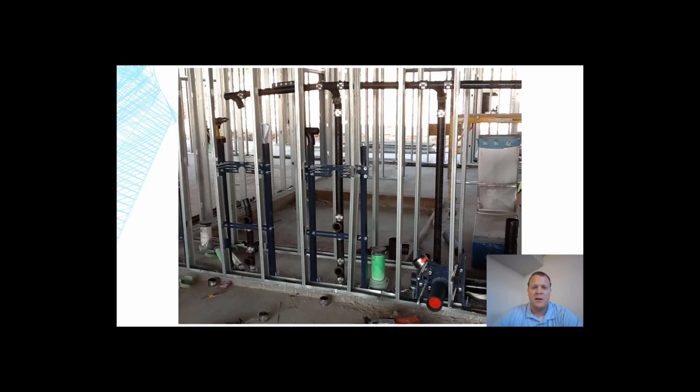So you can't just willy-nilly put in the electrical on the wall and then expect the drain waste vent to work. Not that there would necessarily be a lot of electrical in this wall, because this looks like some sort of carrier for a toilet or something. But there could be some electrical on the wall, and it would definitely go later. This is a good example because it shows that the pipe, the racks, all that stuff kind of has to go first.